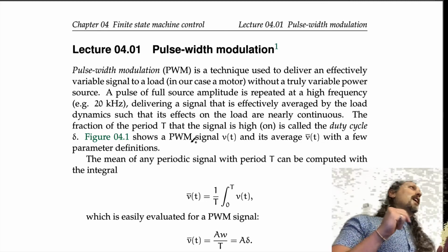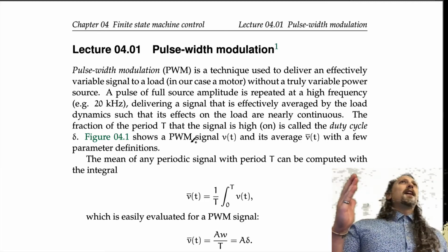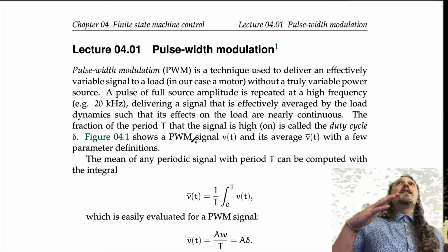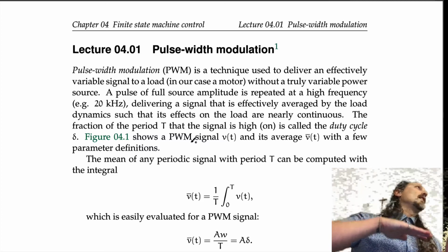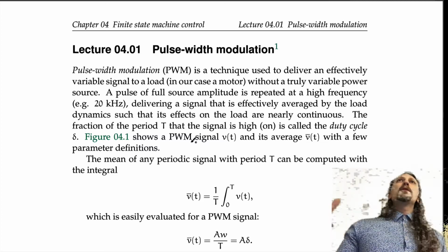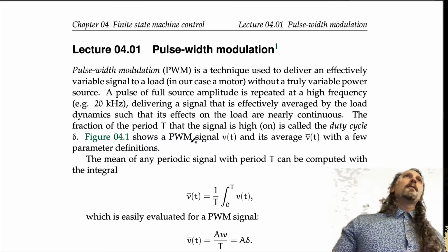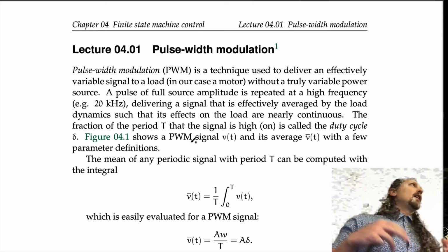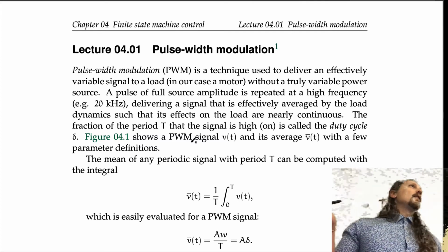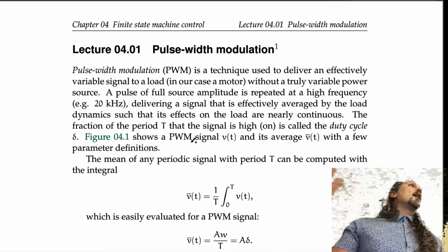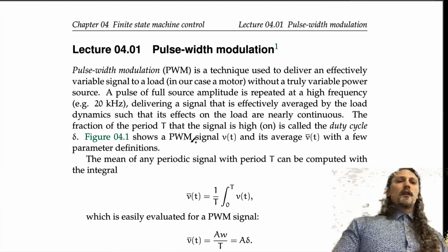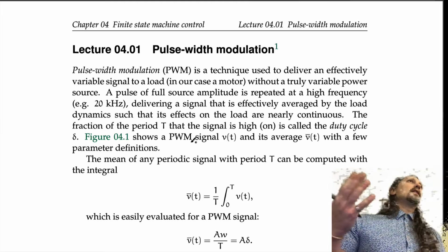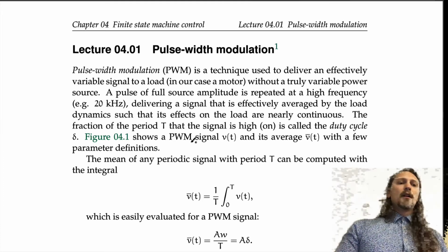Motors just react a little slower than that, right? So it might start moving a little bit, but it's not going to just rocket up in speed and then drop down. And that's mostly because of its inertia, right? So effectively that sort of averages out the pulses that you apply to the motor. And just the dynamics of the motor allow you to...